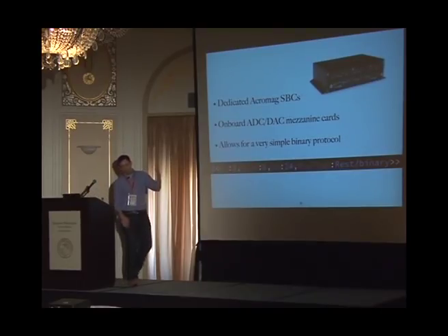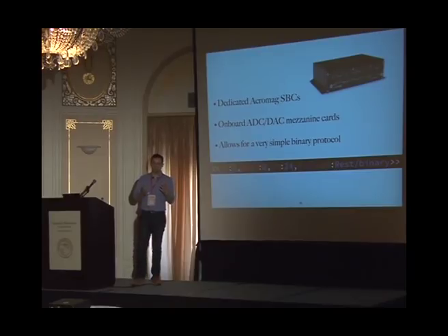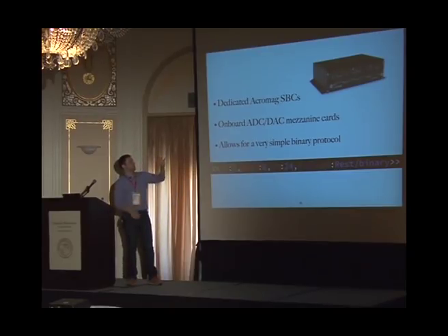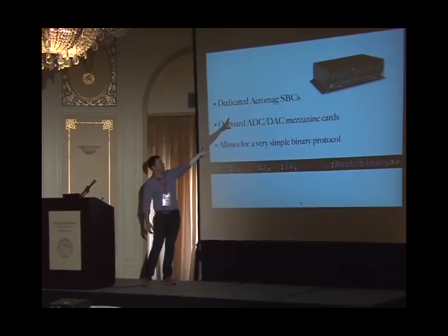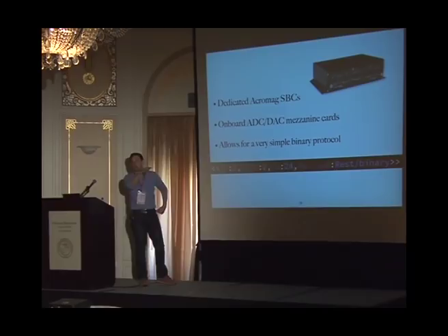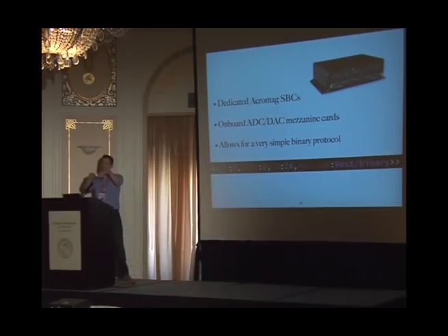So there's a company called Acromag. They make a lot of dedicated hardware. In particular, we used a product of theirs, which is single board computers with basically field I/O points. In the picture up in the top right, there are 4 slots on the bottom of that device. Each one has a little card that fits into that slot, and then you have a nice jack on the front that you can plug into. Each one has either an analog to digital converter in it, or a digital to analog converter, or digital I/O. And each one provides something like 24 channels of I/O. So you have 24 channels times 4 cards per little single board computer.